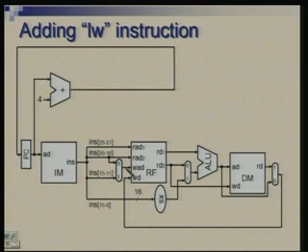This is the choice which will be taken for load instruction, this is the choice which is taken for add, subtract, and or SLT instruction. Okay. So, this is the complete picture for the 7 instructions we have done: add, subtract, and, or, SLT, and load, store. Everything which is required for these as far as data path is concerned is there.